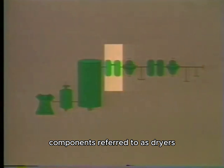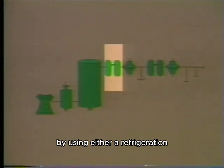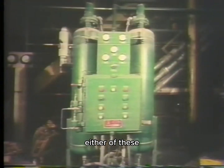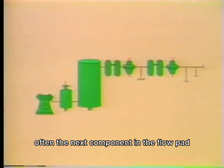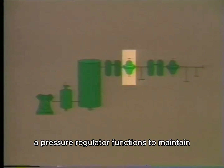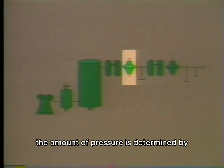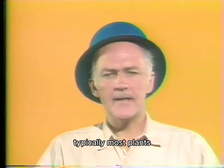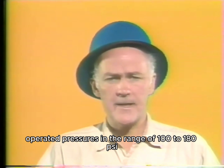Components referred to as dryers are used to remove some of the moisture and contaminants in the air by using either a refrigeration condensing process or a moisture-absorbing chemical. Either of these act to further filter and dehumidify the air. Often the next component in the flow path is a pressure regulator. A pressure regulator functions to maintain a constant pressure. The amount of pressure is determined by the requirements of the plant and plant design. Typically, most plant station air systems operate at pressures in the range of 100 to 180 psi.